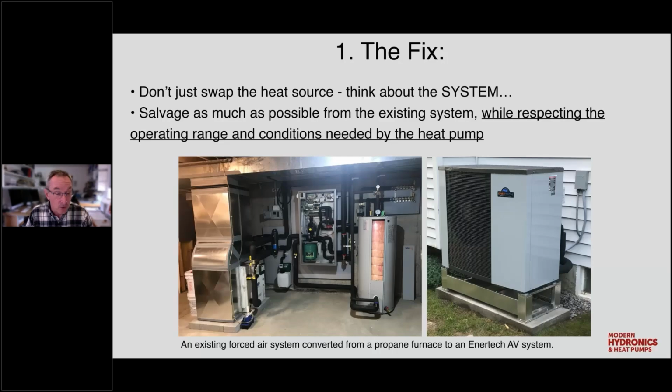I just want to show this. This was a retrofit of an Enertech AV system. And over here on the left, what used to be here was a propane-fired furnace. And you can see the existing ductwork up above. The ductwork was examined. It was deemed suitable for the airflow rates that the air handler would provide. So this is an example where the existing duct system was salvaged, and it was supplied now from a new air handler, and that air handler is supplied from the Enertech AV system.